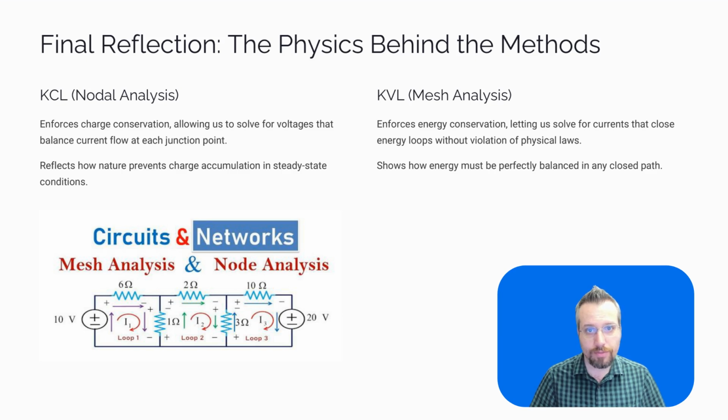So what did we really do? We started with Newtonian physics and field theory. We saw how KCL comes from charge conservation and KVL from energy conservation. Then we built two powerful tools. Nodal analysis, which is good for solving for voltages using KCL, and mesh analysis, which is good for solving for currents using KVL. And through examples, we saw these methods in action, not just mathematically, but physically. Every time you solve a circuit, you are solving how nature balances itself, ensuring charges don't pile up and energy isn't lost. These methods are not just computational, they're deeply expressive of the physical world.